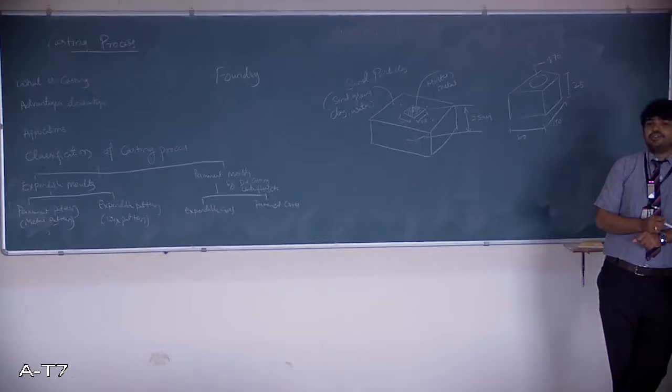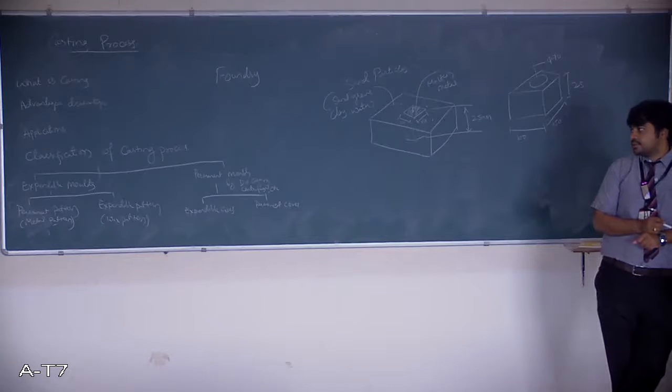Then it cannot be used for job shop production. Okay. For one component or two components, you cannot go for casting. It is uneconomical. So that is one of the demerits of this particular process.